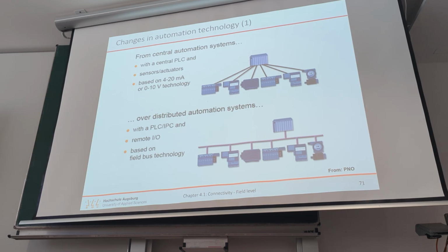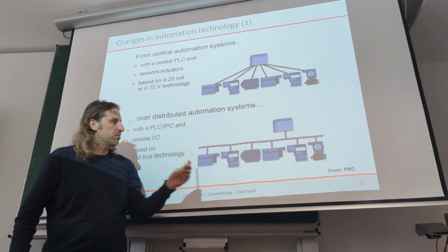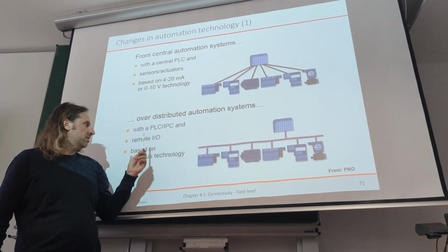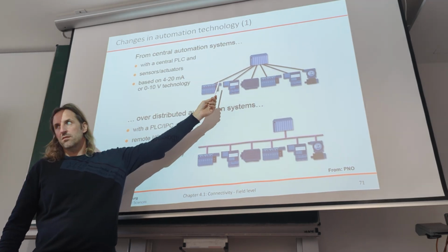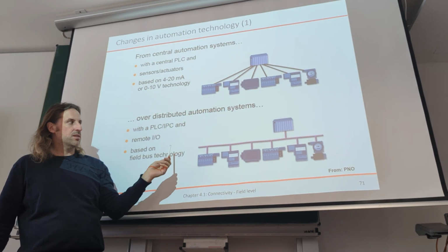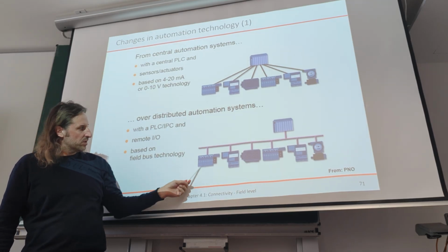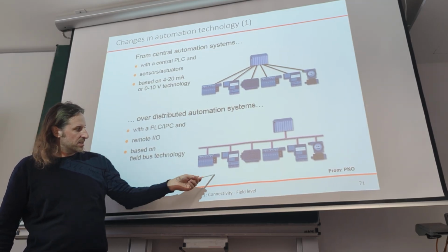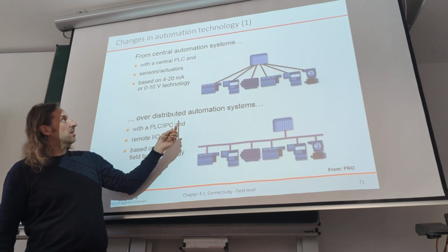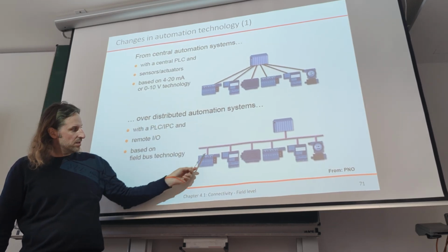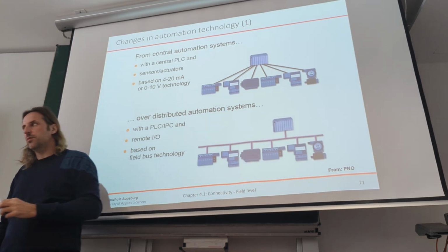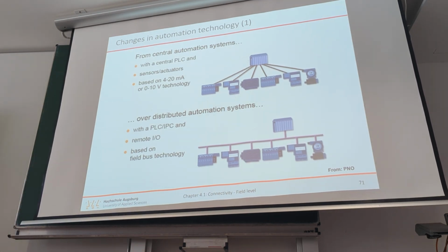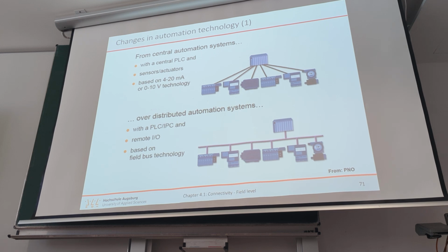Here you see everything is distributed based on a field bus, and in reality we have remote I/O that still connects as a star system, so that connects sensors and actuators. Here we would have the I/O, and then the sensors and actuators connected as a central remote I/O, but not all of our automation components are actually distributed, only the ones that are expensive enough.